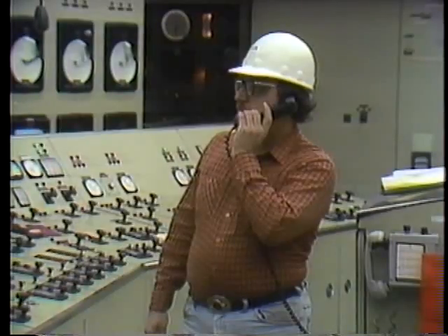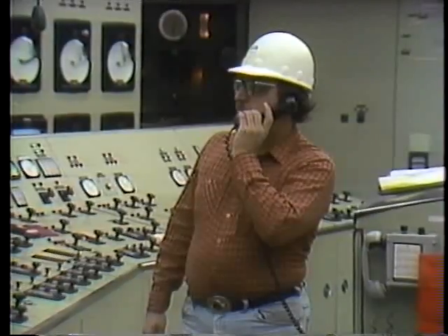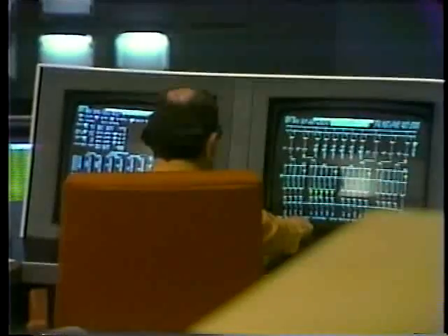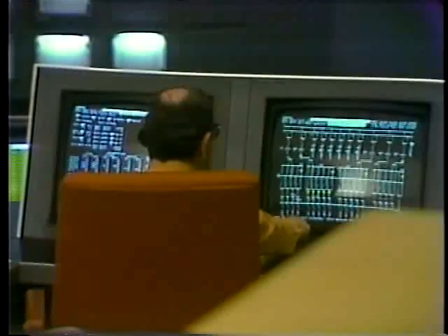Once the loss of flame has been dealt with properly, the operator should notify supervisory personnel and the load dispatcher. Keeping everyone that depends on your unit for the production of electricity informed will ensure that the supply of electricity to your customers will not be interrupted.